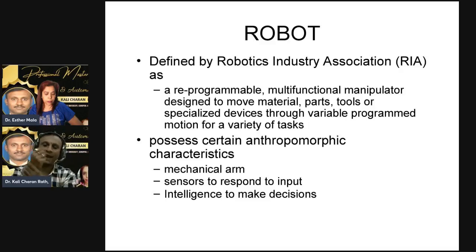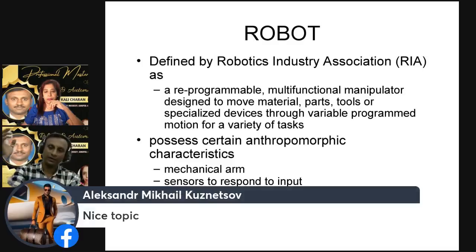End effector means at the end what will be there. This is known as your end effector. Here a gripper or any tool will be there for operation, etc. So the end effector is nothing but the end part of the robot, and our target is that the end effector will reach our target position. Clear? So based upon that, when we are making the program, the mathematical transformation comes through a uniform matrix, and that mathematical calculation is done automatically. When we give the range, based upon that range, the manipulator will drive and the end effector will reach the target coordinate value.